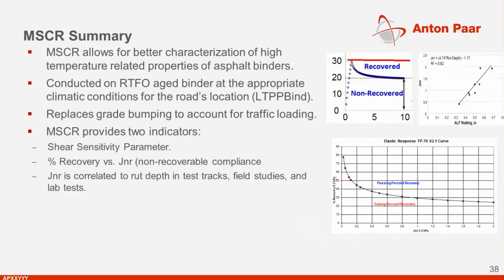To summarize, the MSCR test allows a better verification of high temperature related properties of RTFO and polymer modified binders at the climatic conditions for the road location.